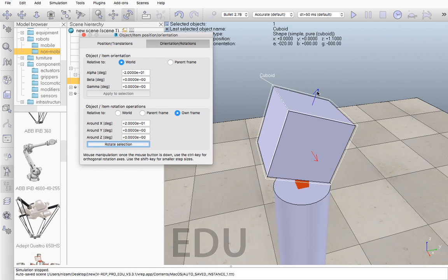Now if I want to rotate it about z by 30 degrees, what you do is delete this 20 and input 30 in the z. I'm deleting this 20 because if I leave it enabled here, it rotates in both x and z directions.